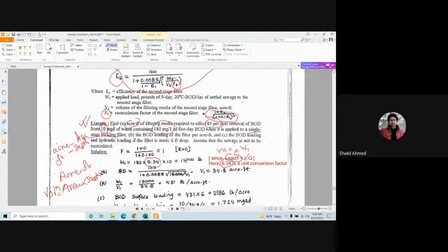Therefore, if you put rho in milligram per liter and Q in million gallon per day and multiply with 8.34, so 180 milligram per liter times 10 million gallon per day times 8.34, you'll get this in pound per day. They didn't write it explicitly, but this is pound per day.